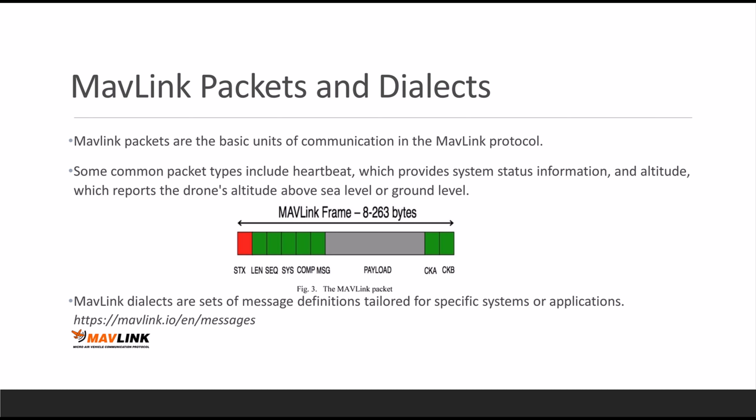They are independent and they are communicating with the ground station and other nodes. And what makes it even more crazy is that in the middle of all these communications, you send a command, for example a flight mode change, to your drone. In that case, none of the receiving frames would be interrupted, and in the meanwhile you are going to send another packet to the drone, this time with the same structure, but the message is different, the payload is different.